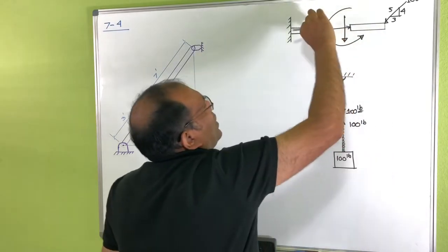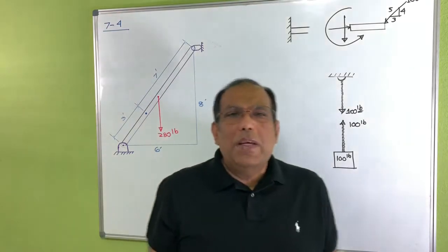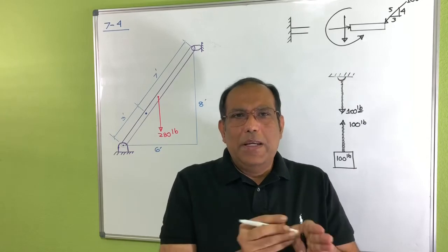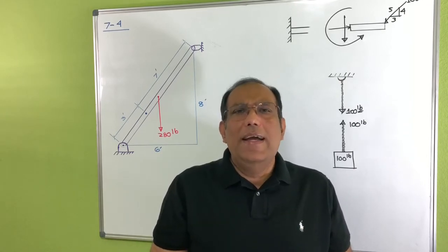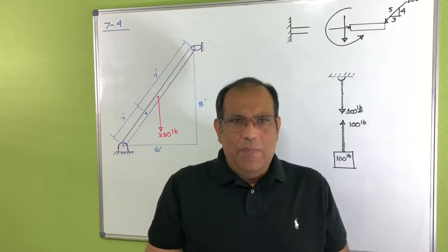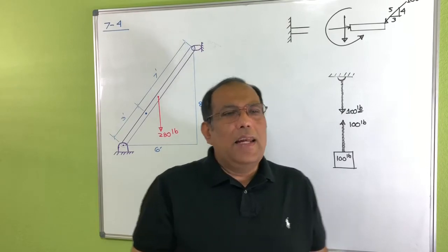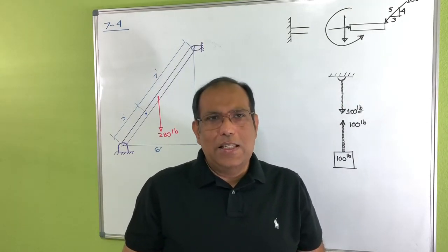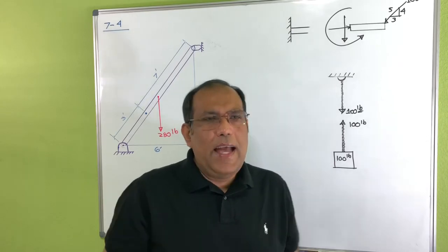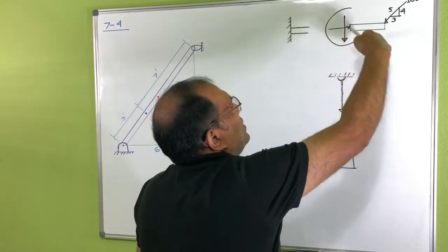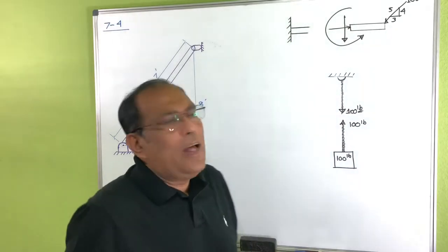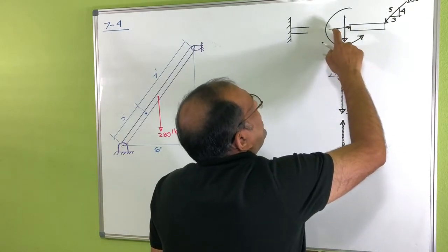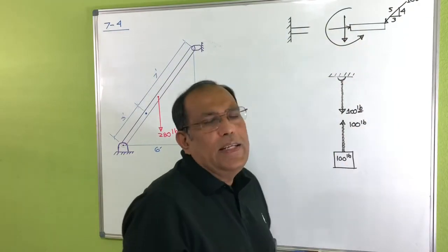This one we call the normal force, which is basically perpendicular to the cut surface, okay, perpendicular to the cut surface or along the longitudinal axis of that member. And shear force is perpendicular to the longitudinal axis of the structural member. And similarly, this one is your bending moment. Now if this one is in equilibrium, then you can find out this one and this one quite easily.